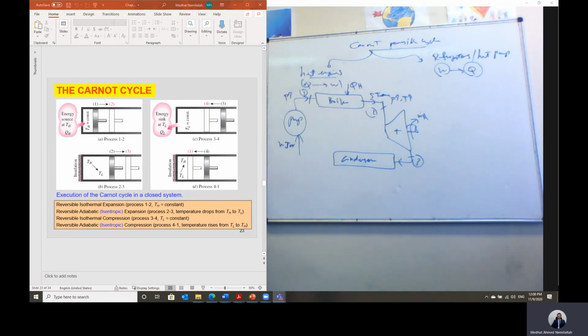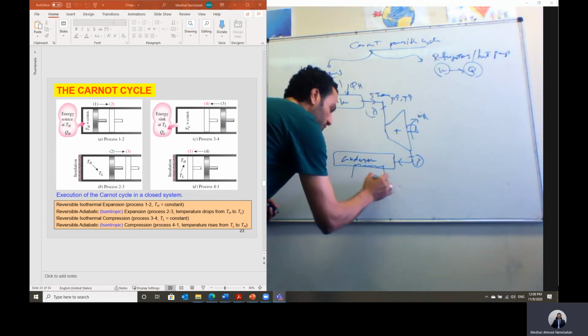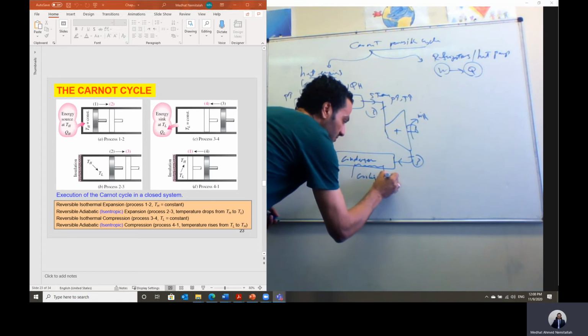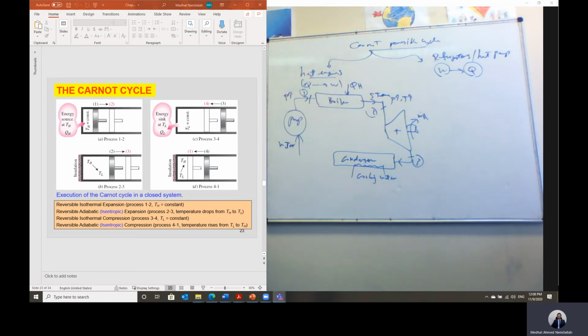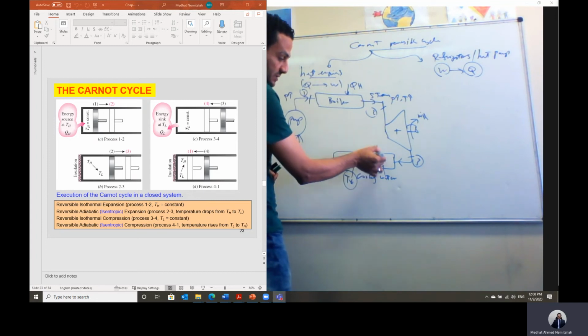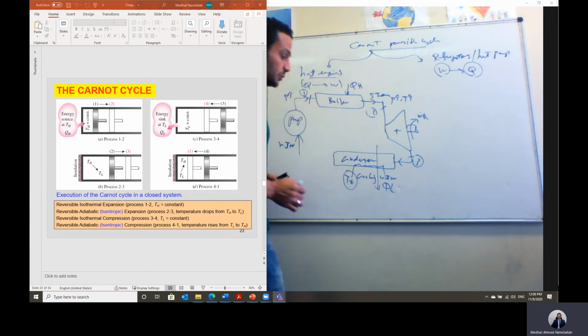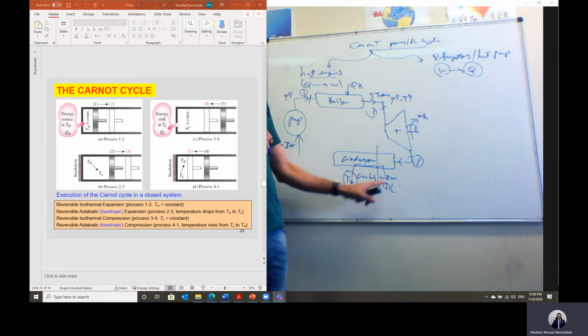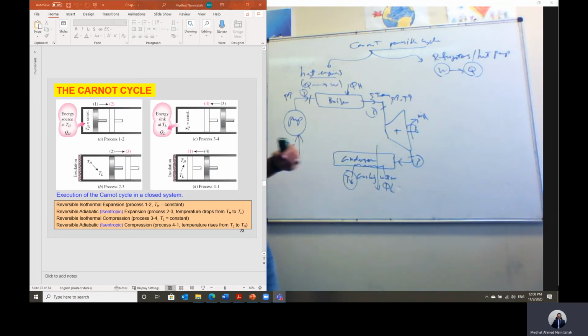A condenser is a heat exchanger in which we have cooling water. In most cases for a steam power plant, we have cooling water coming at low temperature, so it comes here. This cooling water will absorb the heat. So heat is rejected to the cooling water from the flowing steam. We call it Q low because heat is rejected at the low temperature. Then this saturated mixture of steam will be converted back to water at state number 4. Then this cycle is repeated again, to generate continuous work out of this cycle.